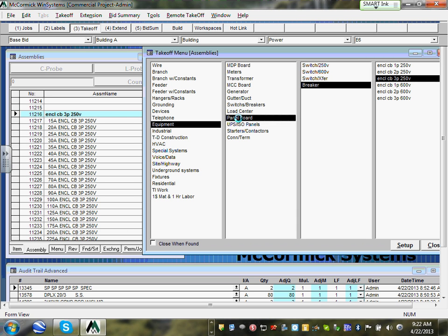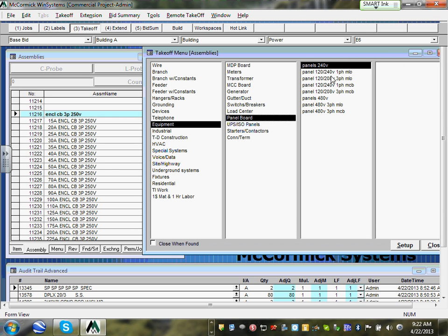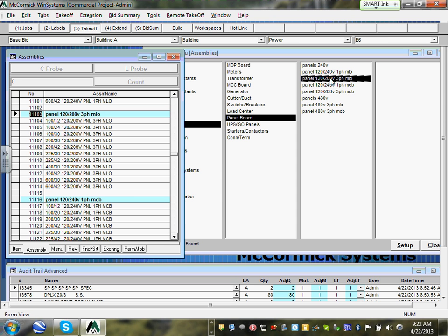And then you can go to panel boards. Here's a bunch of panel boards, guys. 208, look at the 208 3-phase. By the way, this project is not 4,000 amp, right? This is the 400 amp. I keep forgetting, we're doing the commercial project. When you do the industrial, you're going to find it. And here's all your panel boards, guys. You can find 225 all the way. Remember, our system is 208/120, so you're going to be right in here.